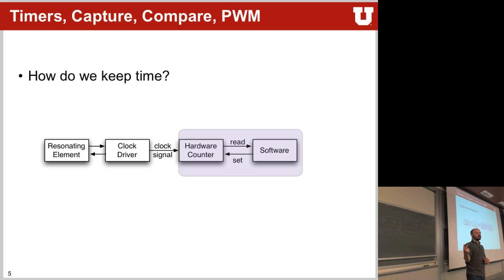So now you have counting clock ticks. Let's say you had 257 ticks. How can you now relate that back to actual physical time? You use your clock frequency, exactly. That way you can now figure out how long it took in real time for the wheel to spin around. So that's what captures are used for, okay?